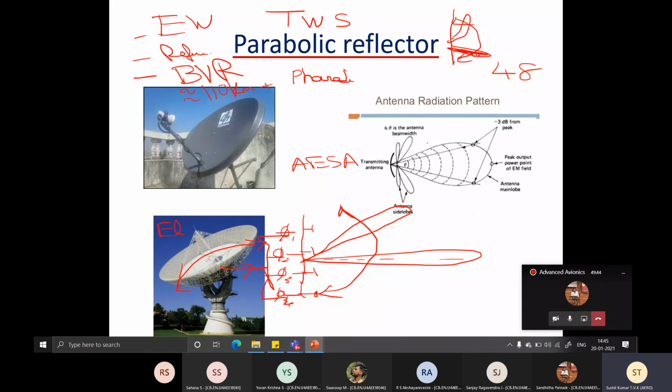And people should go a bit more and see, apart from the electronics, what is that propulsion system which is challenging in BVR missiles? The problem with missiles is that once you launch, let us say at the end of 50 kilometers, it doesn't have much energy to maneuver. So if the aircraft was initially here at the end of its maximum range and has maneuvered in this direction, the missile really doesn't have the energy to accelerate. So you can easily dodge these missiles. That's what happened when these F-16s fired those missiles. The Su-30s were able to take evasive action. They knew the missiles were coming, so they were able to dodge them. But now some propulsion systems are being developed so that at the fag end of its range, it can still have sufficient energy to carry out such maneuvers.